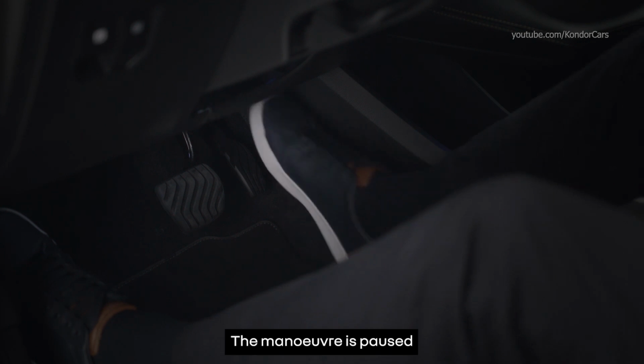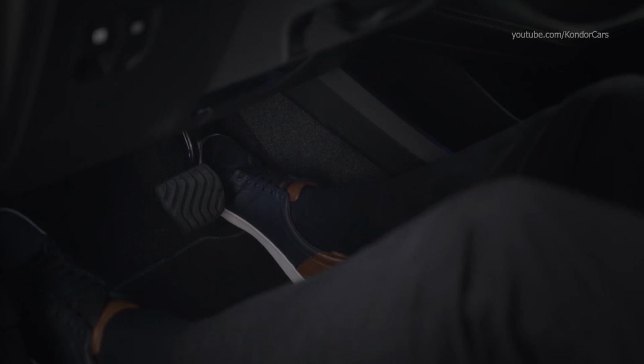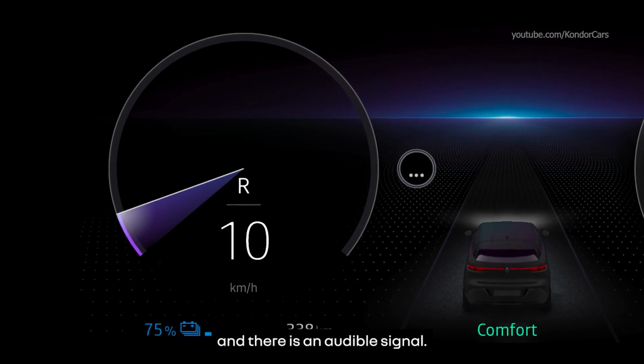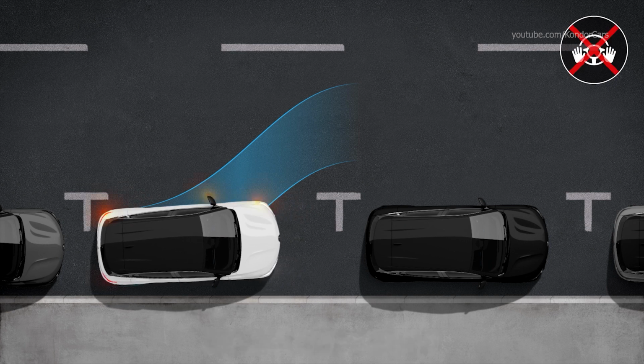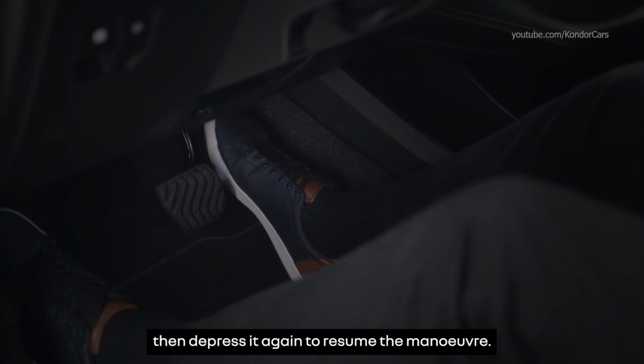The maneuver is paused when you depress the accelerator pedal beyond the kickdown point. The indicator light on the instrument panel goes out and there is an audible signal. The vehicle is now immobilized. Release the accelerator pedal, then depress it again to resume the maneuver.